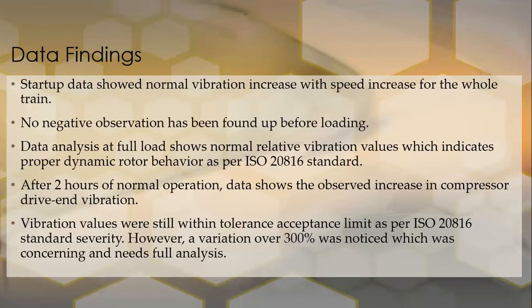The startup vibration data showed a normal vibration increase with speed increase for the whole train. No negative observation was found before loading. Data analysis at full load shows normal relative vibration values, which indicates proper dynamic rotor behavior as per the ISO 20816 standard.